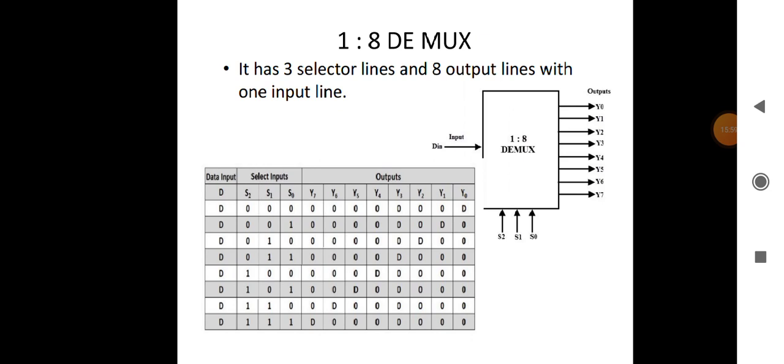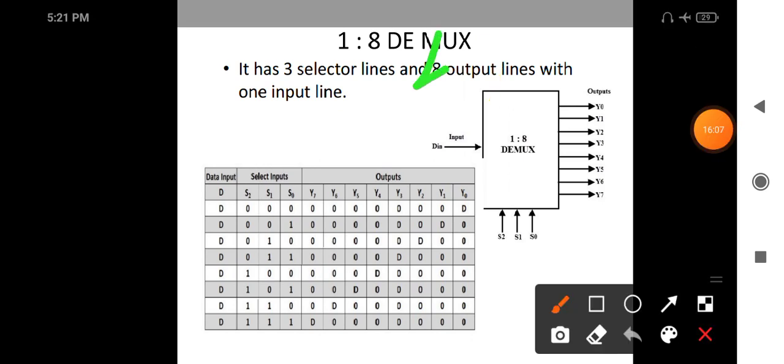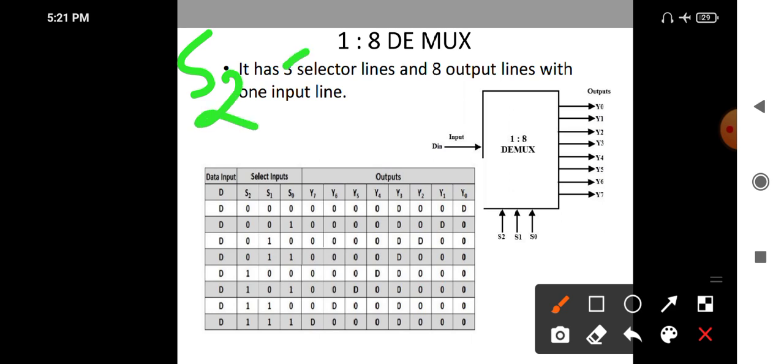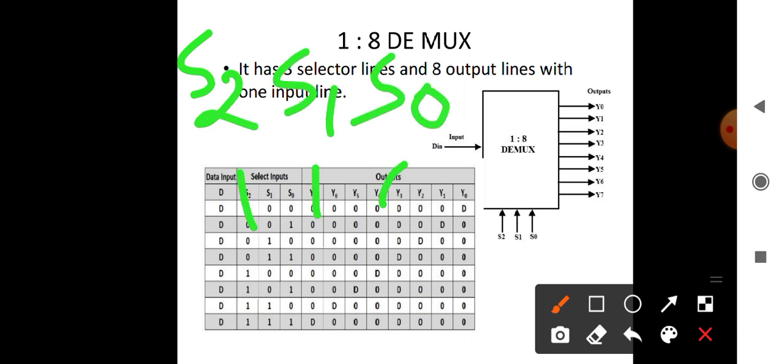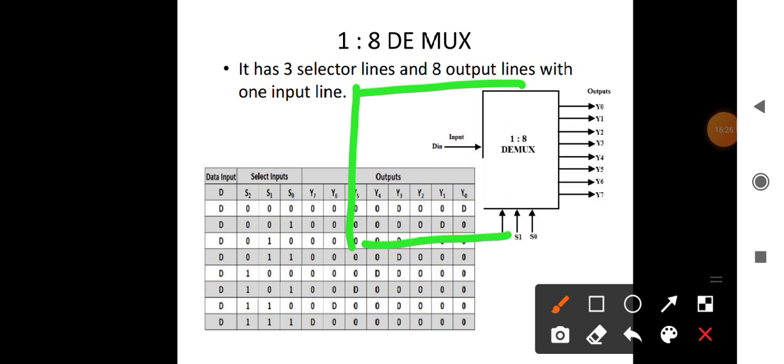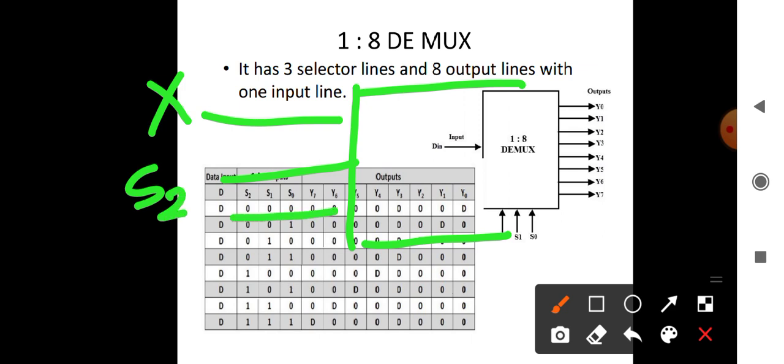This forms your D5. For that I will just write it down and I will show you. See here, for say D6, we have 4 2 1, that is 110. So for that, S2, S1, S0 is 110. Then we can have a 4 input AND gate: X, this one S2, this one S1, and S0 we need to take from the NOT gate.